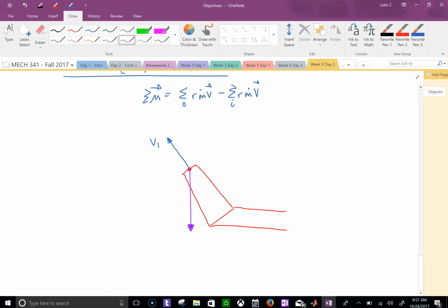We're going to break it up into this component, straight up and down, okay? This is your velocity of the nozzle or the sprinkler, right? Because the sprinkler is actually rotating this way. This is your tangential velocity, okay? Does anybody remember what that equation was in physics? Tangential velocity, if you know omega and you know the radius? I'll give you a hint. You use omega and radius. Yes, you just multiply them, R omega. Okay, so we'll get to that.